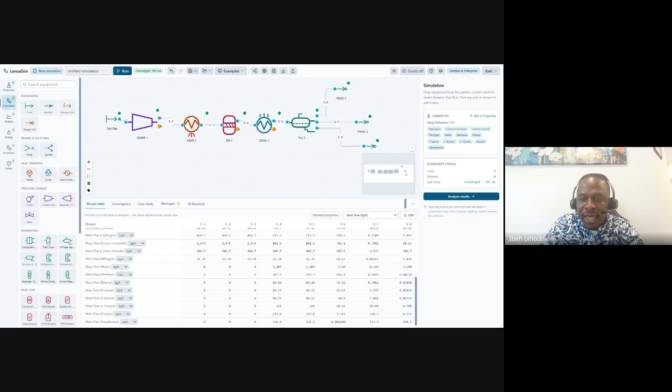There's more methane here and less methane here and here. That makes sense, right? These are more of the unreacted gas. But as you have more of the liquid hydrocarbon in stream S7, if you come to S7 now, I should see more of hexadecane. You see 173.5, 228, we have more of those liquid hydrocarbons here and here. Does it make sense to you?